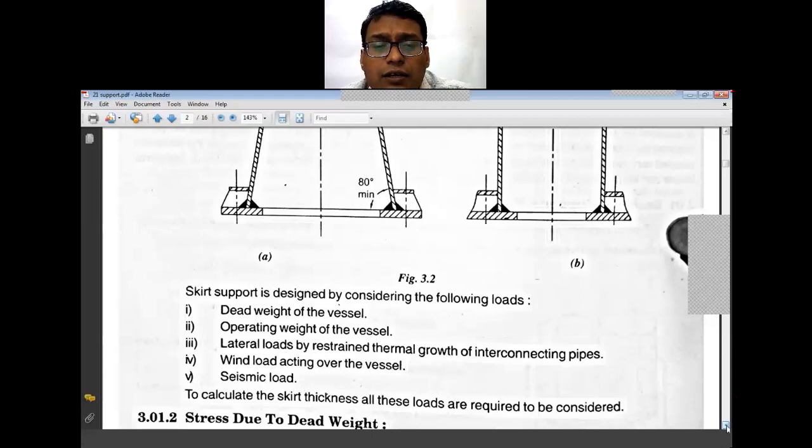So if the vessel is a tall vertical vessel, then the wind load acting on the upper part will be higher because of the wind as compared to the lower section of that vessel. Now, what can be the vessel height? Vessel height can be 10 meter, 20 meter, or even sometimes 30 to 50 meter. That depends on your purification capacity or the vessel dimensions.